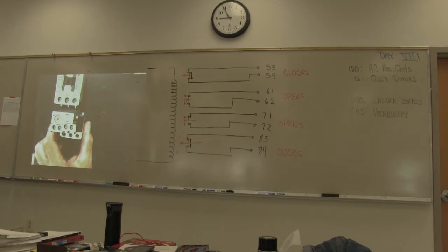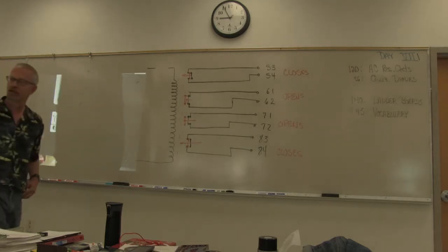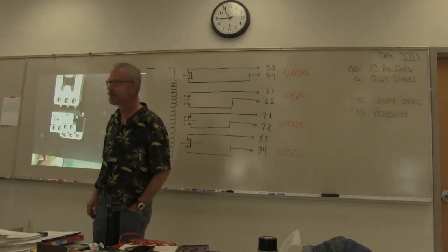I mean, is it reading, I'm not sure. It doesn't say. Is it reading the air temperature? Is it reading the temperature of the wires? Or is it reading... I think it's the motor. It's reading the current, the temperature that's generated by the current in the wires. It works the same way that a circuit breaker works. It's always based on heat, right?